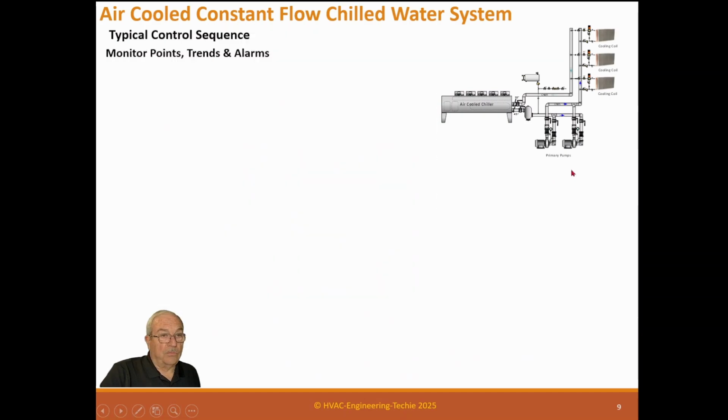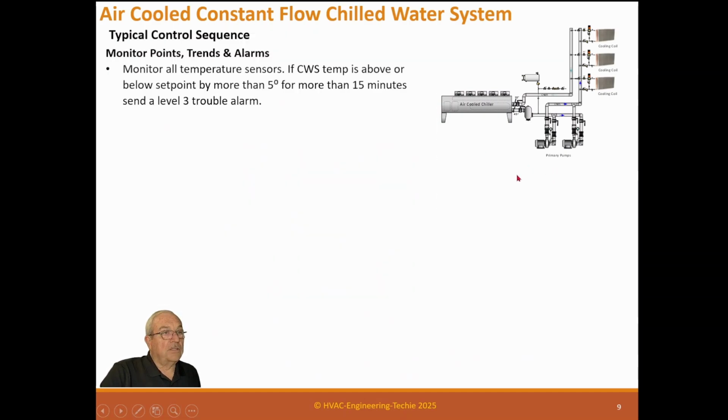These will work well. Monitor trend points. Monitor all temperature sensors. If the condenser water or chilled water temperature is above or below set point by more than 5 degrees for more than 15 minutes, send a level 3 trouble alarm.